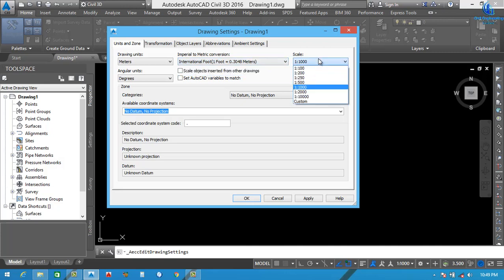Next, scale depends on you. Normally we keep 1000 here. We can also change it from here. This depends on when we start the proper drawing. Angular unit, next we select radian here. After that grades and degrees. These options differ, because sometimes in the beginning this type of tool used grades, and after that we now use degrees. Okay, we prefer degrees. Click here.